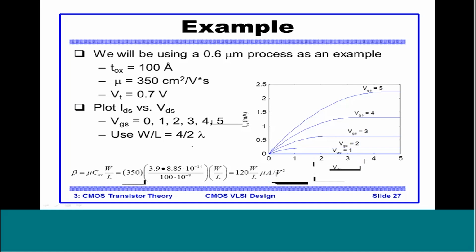So let's go through these IV characteristics. If we notice the first part of the curve, it is very similar to the Ohm's law curve. That means it's a linear region where ID is increasing with increase in drain voltage. These different curves correspond to different values of VGS.